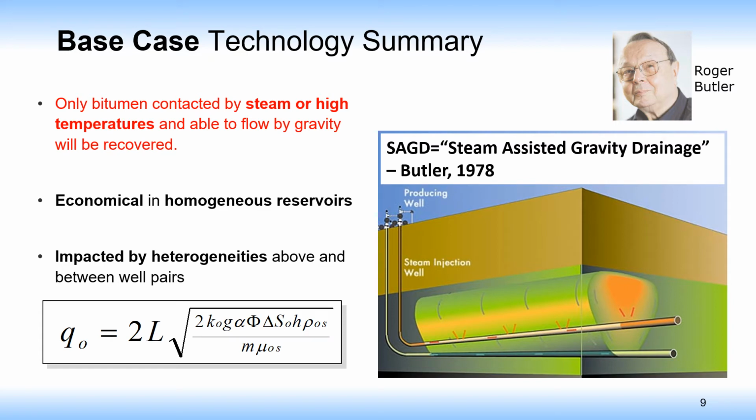And so here's a rate equation, and the flow rate in that producer is directly related to the length of the producer, or the effective length, how much of that producer is in the pay zone. And so we need to evaluate that. We also have in the flow equation a permeability term. That's very important, vertical perm.